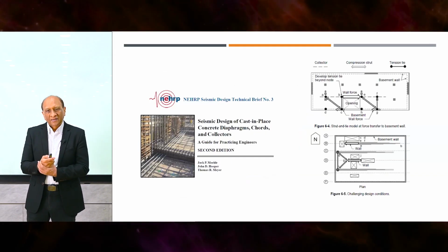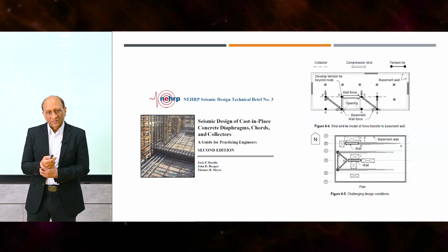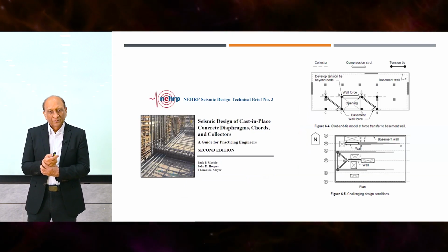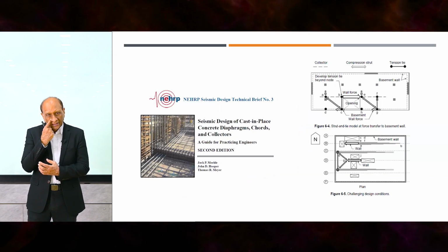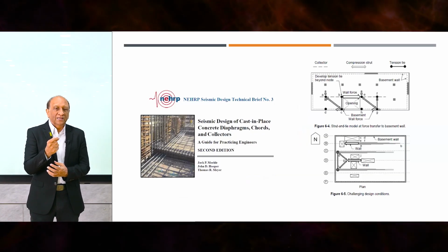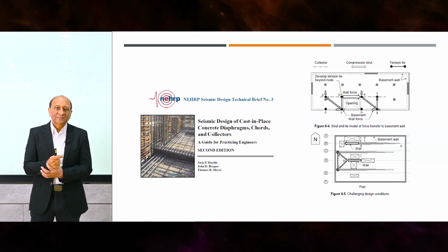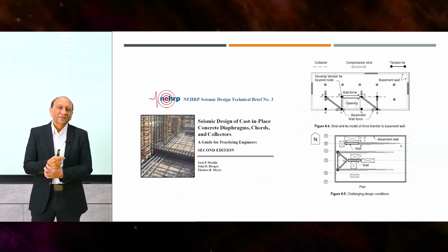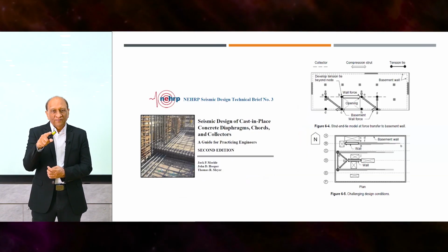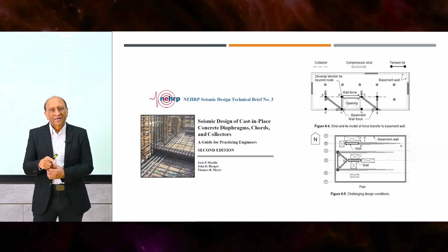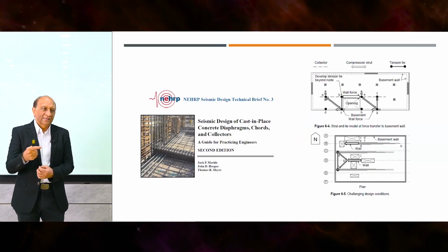This is another document that most people use, which is quite a good document, especially for tall buildings. But this uses the chords and collector method. But within that document, they also have a strut and tie alternative, where they say that around the opening, you can find a strut and tie mechanism and design accordingly together with the collectors.